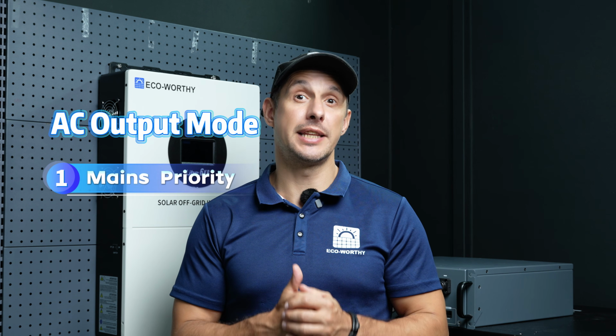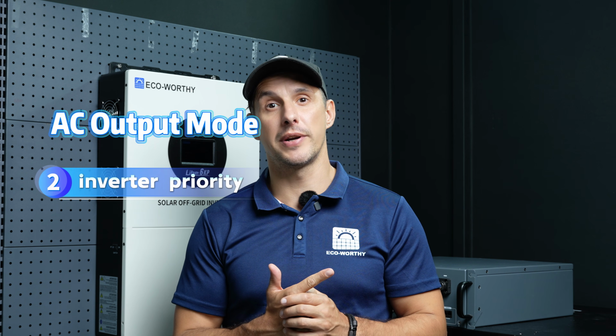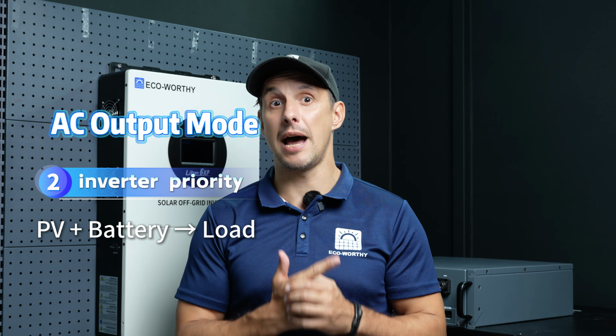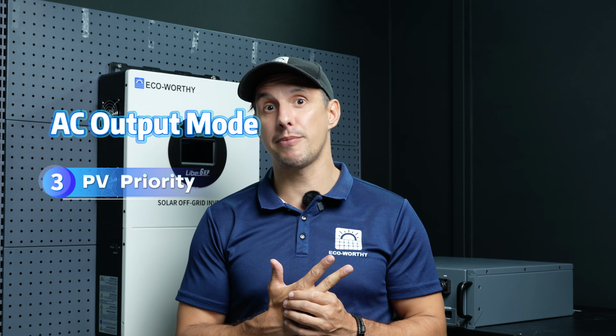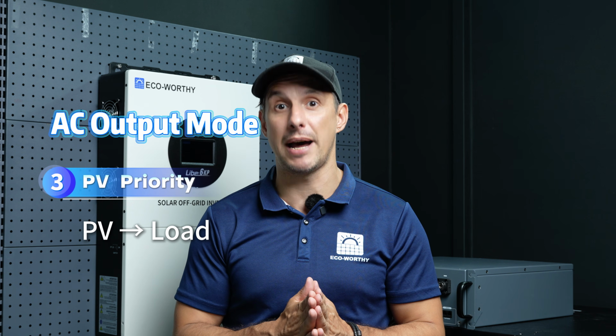Choose mains priority if you mainly want to keep the battery as backup power. Choose inverter priority if you want to rely more on solar and battery power. And choose PV priority if you want to use solar first while keeping more energy stored in the battery.